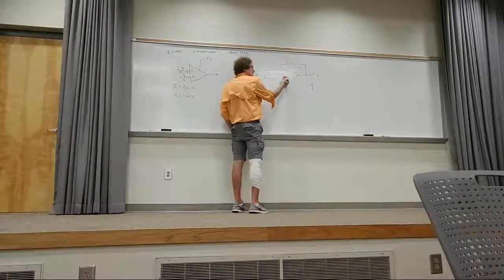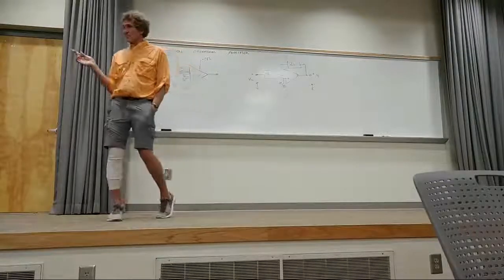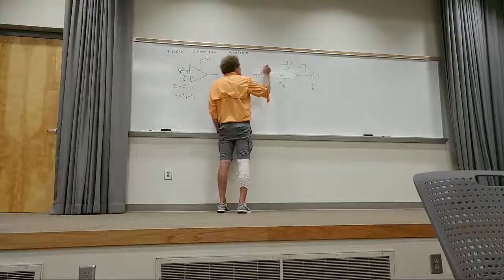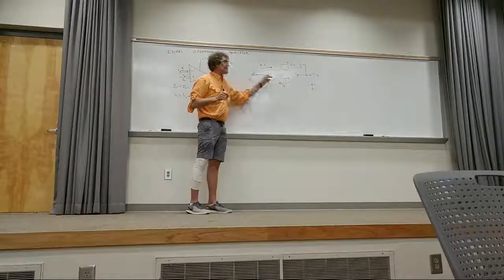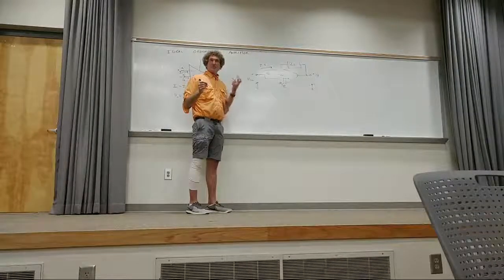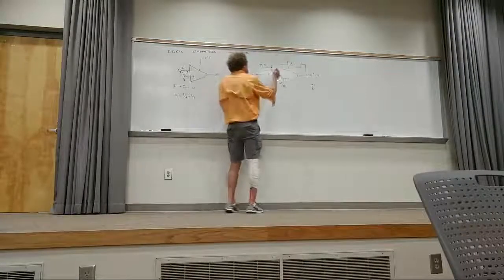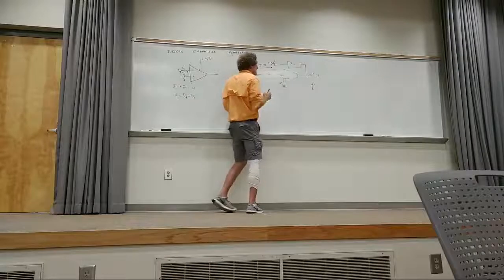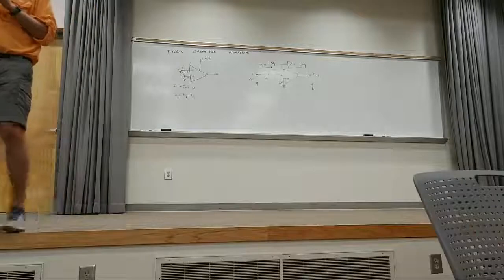How many volts at the negative terminal? If it's 0 here, what is it here? 0. Has to be 0. Remember, whatever's on the positive is on the negative, whatever's on the negative on the positive. Now that said, how much current is going this way? Vn minus 0 over Z1, isn't it? The voltage difference across the first impedance, right, divided by the impedance. So that's simply Vn divided by Z1 is I1. Do you all agree with this? Yeah. Everybody with me? It's straightforward.